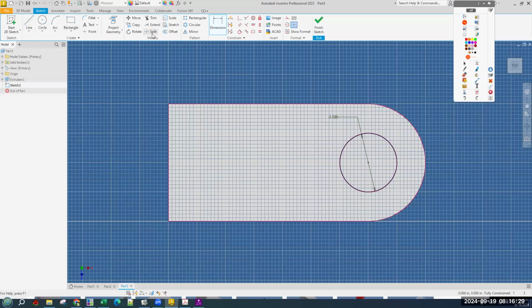And again, you can use work points and dimension it, but for this situation, it's easier to just draw a line 2 inches tall, snap it to horizontal, and it will give you enough constraints to save you some time. We're making this line just so that we can use the other end of it as the center point. And the center point is here, and it is a diameter of 2.